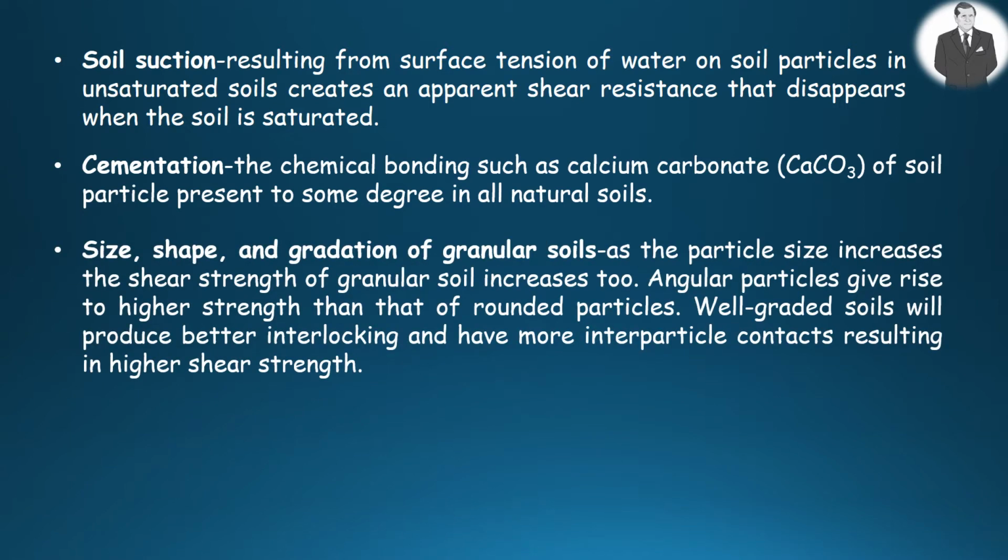Finally, size, shape, and gradation of granular soils. As the particle size increases, the shear strength of granular soil increases as well. Angular particles cause higher strength than rounded particles. In addition, well-graded soil will produce better interlocking and have more interparticle contacts, causing higher shear strength.